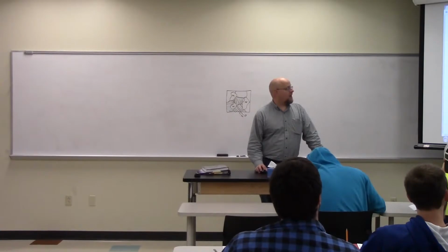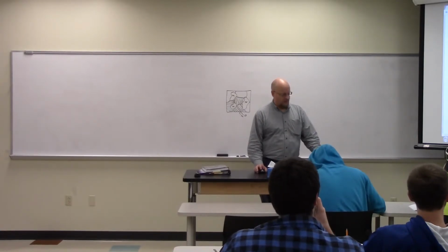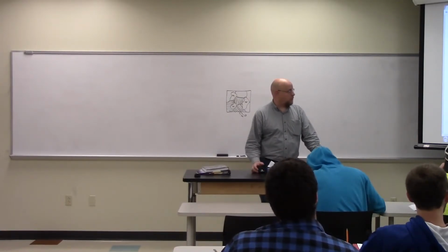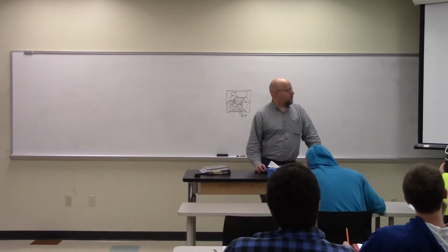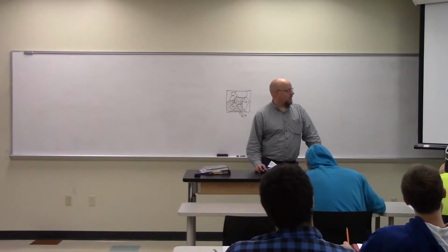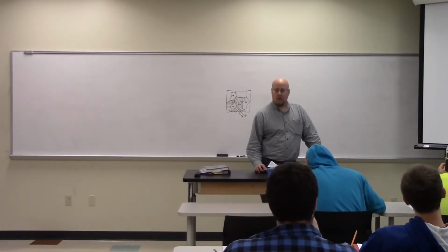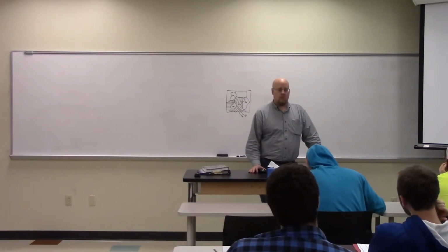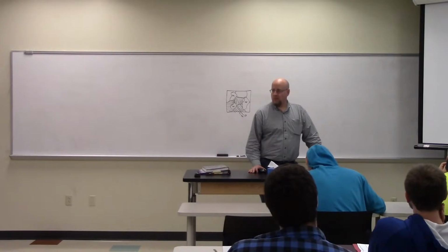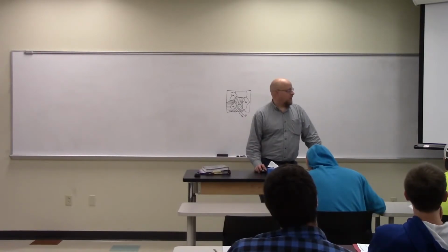Be able to describe the evolution of microstructures as you cool down the phase diagram, so kind of like what we were just talking about. Be able to show what happens if I cool from here down: I form some alpha, then it's all alpha, and then what happens as I start to get down here? Beta forms at the boundaries. Right, beta forms at the grain boundaries.